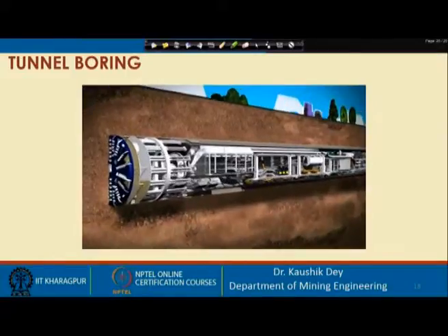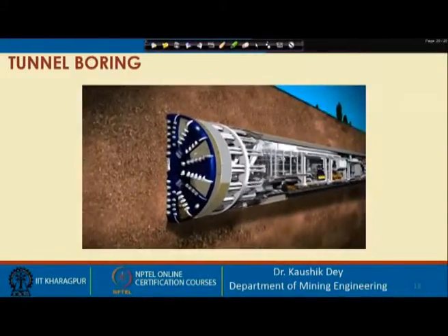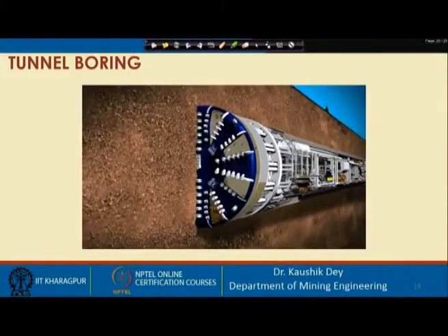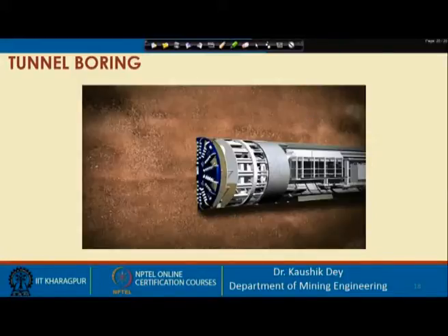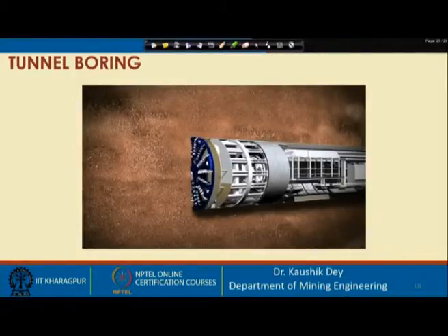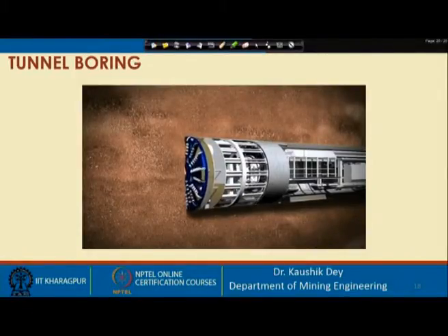And the next is the earth pressure balanced TBM, which will be used for tunneling in waterlogged conditions such as underground below the Thames. Mixed shield TBMs use bentonite, which is a slurry of clay and water, to support the excavation face and act as a suspension medium for the excavated material.